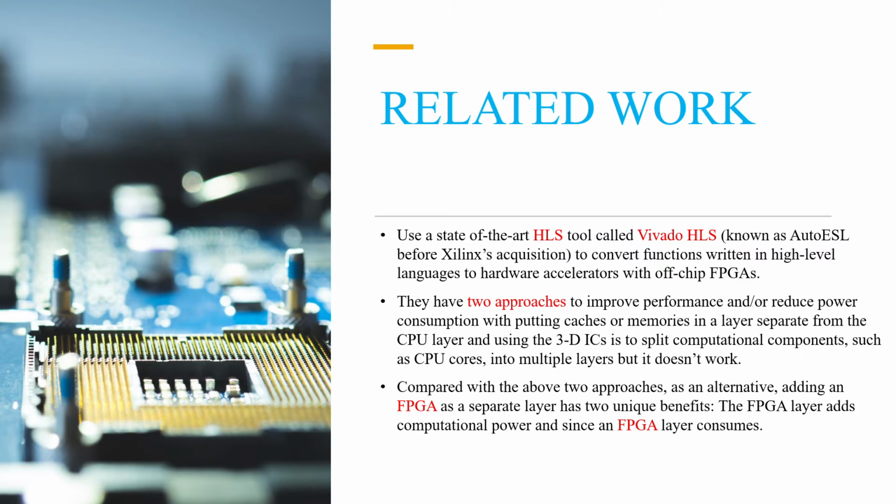Fortunately, recent developments in HLS have significantly lowered this barrier. HLS tools directly convert functions written in a high-level language to hardware accelerators. Some researchers have also studied the direct translation of Compute Unified Device Architecture (CUDA) or OpenCL, designed for heterogeneous parallel computing, to hardware.